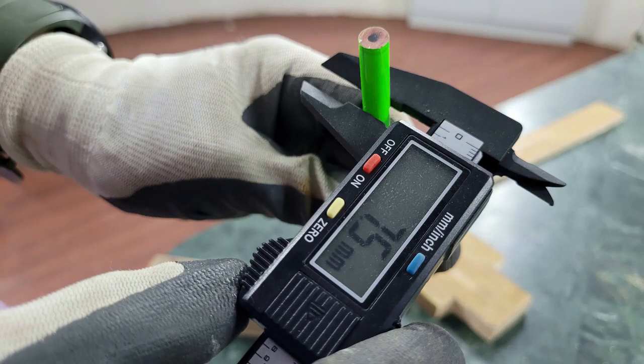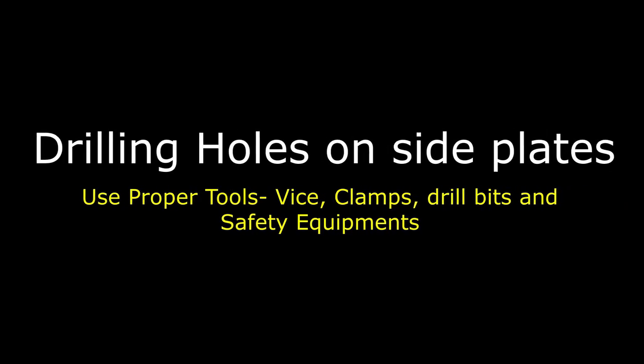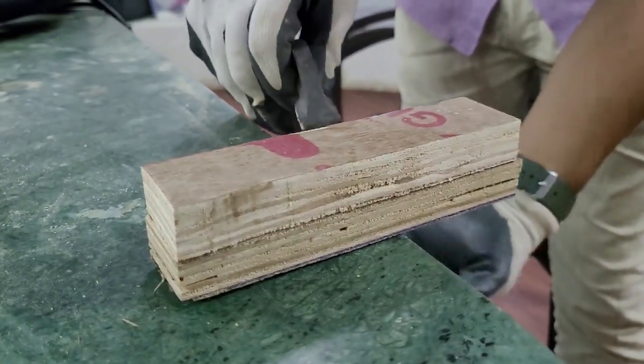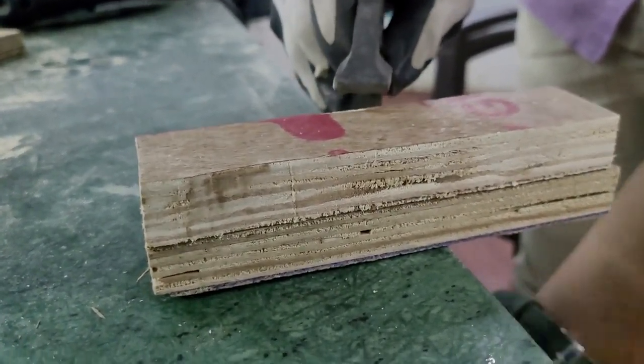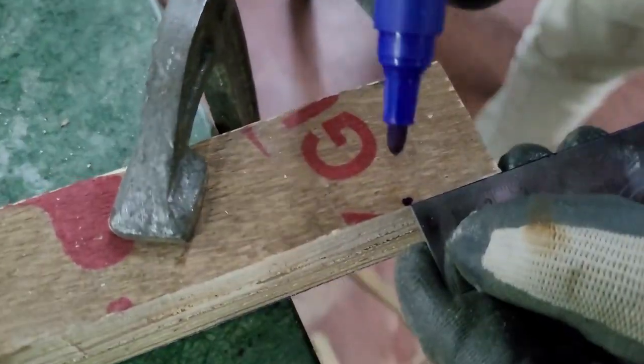Now we are going to use pencils as a fulcrum mechanism. They are 7.5 millimeters in diameter. So we are going to use a drill machine to make holes of 7.5 millimeters in the side plate. There are two holes along the side plate. So we are going to clamp two side plates together.